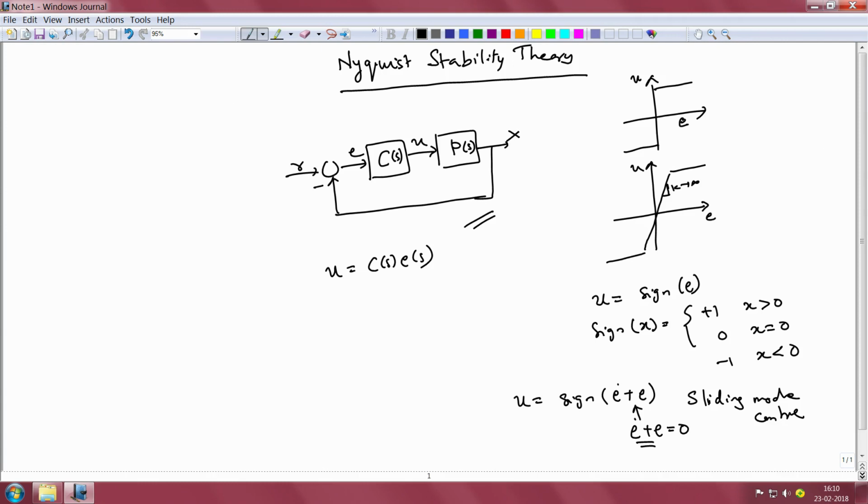Now, one would naturally want to wonder if this notion of high gain is also valid in case of linear control systems. Indeed it is so, but it is not easy to visualize it if one were to stick to the Laplace domain. However, it is obvious when one goes to the Fourier domain.